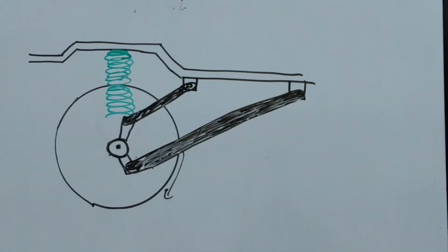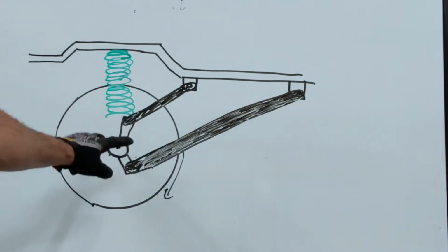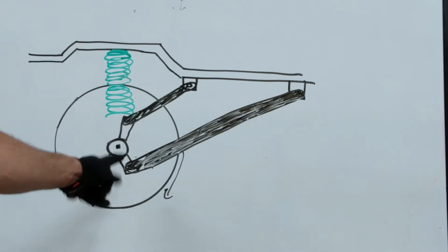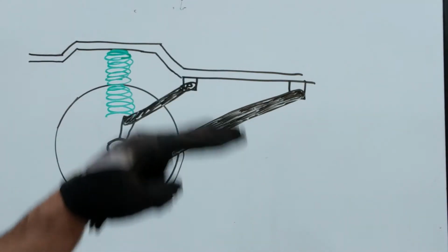This is a typical configuration of a 4-link suspension, where we have control arms or radius arms on 2 sides of the vehicle, upper and lower. The upper ones are typically going to be a short radius rod, and the lower one will be a long radius rod. And the difference in length is going to change how much they change angle down at the axle and provide optimum driveline pinion angle.